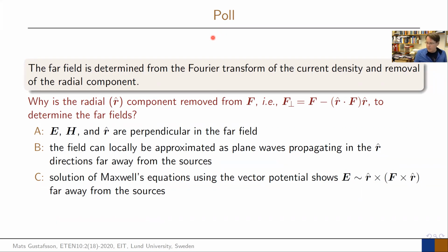So you always will have this case where you transmit from an antenna, typically a dipole, far away of that. So we're talking only now about far field properties of the antenna. Near field can actually be quite different, but we are far away from these ones. Then the power is propagating away from your antenna, and your electric field and magnetic fields are perpendicular to this direction. And think about your right-hand rule there.